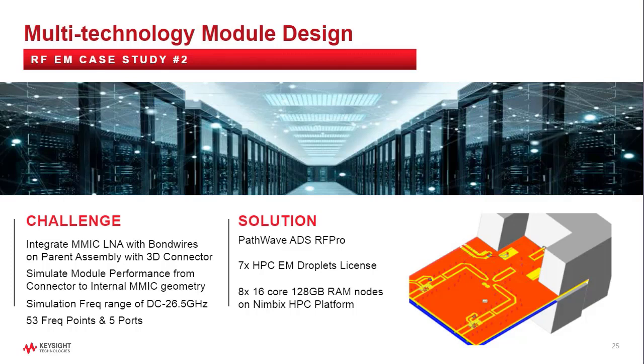Okay, for case study number 2, this is a multi-technology module design. It's actually part of a workshop that we've put together. It's available to anyone that's interested in it. Just let us know after the webinar. We can get that off to you. It's a module that integrates gallium arsenide MMIC LNAs mounted into cavities in the parent assembly, hooked up with bond wires, and then a Southwest Microwave edge clamp mount connector is also included in the design.